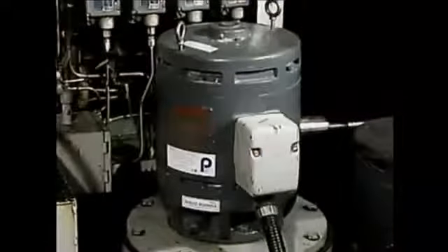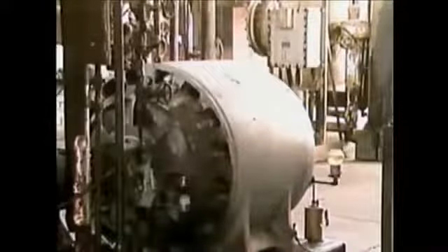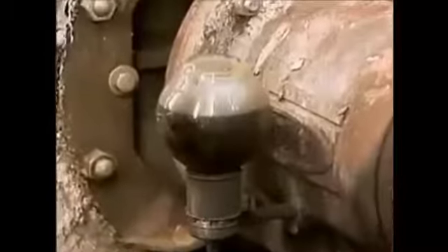Some motors use sealed bearings that do not have to be relubricated for the life of the motor. The bearings of some other motors are greased through grease fittings as part of a regular maintenance schedule. Some motors use constant level oilers, also known as bottle oilers, to lubricate their bearings. The design of the constant level oiler allows the operator to look at the level in the reservoir and add more oil when necessary. When a constant level oiler is used, oil flows into the bearings by gravity.